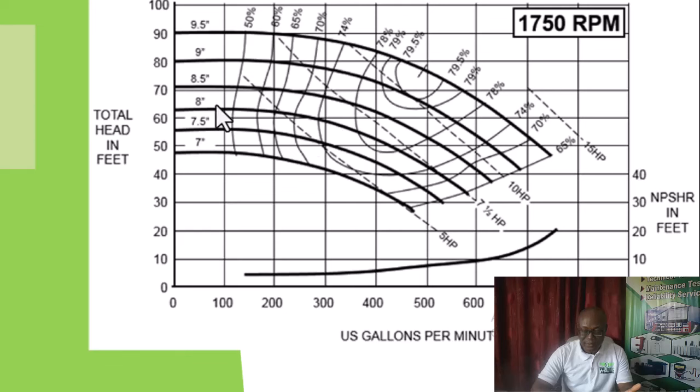Now if you plot this up, the intersection between that 65 and this 300 is about this point. If you look at it, you see that it is between these two particular pumps: a 7.5 horsepower pump, and then here will be about a 9 horsepower pump. Are we getting it? So here is 7.5. The next higher is 10 horsepower.